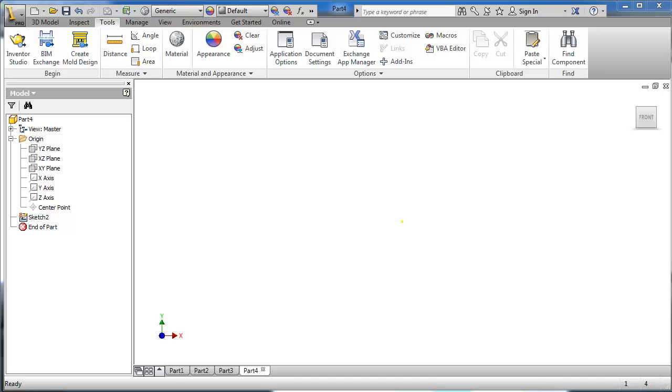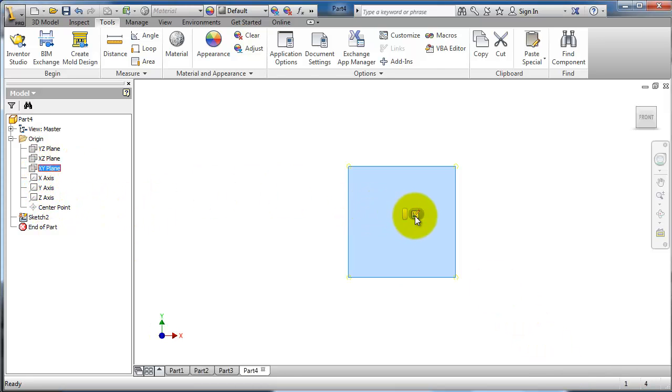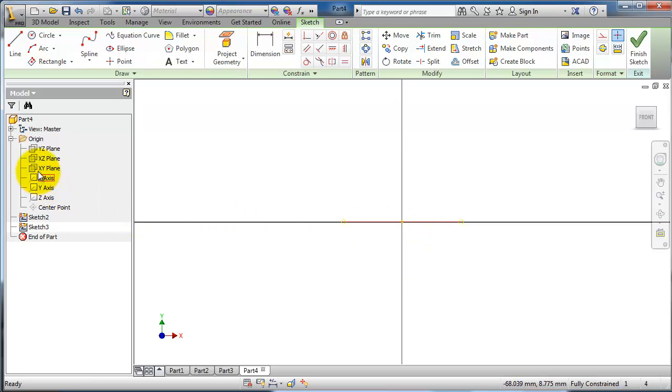This is tutorial number 9 in Inventor, and now let's start a new sketch on my preferred sketch plane XY. We are going to continue talking about the sketch menu, and today we're going to talk about the dimensions. So let's choose the three-point center rectangle, and now when you are moving the point of the rectangle, you can see the dimensions or the XY coordinates on the plane.